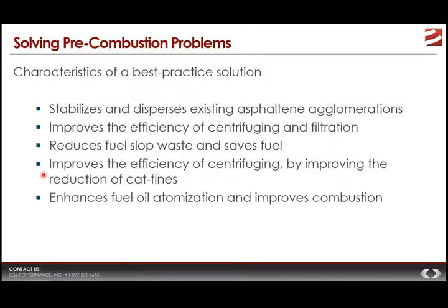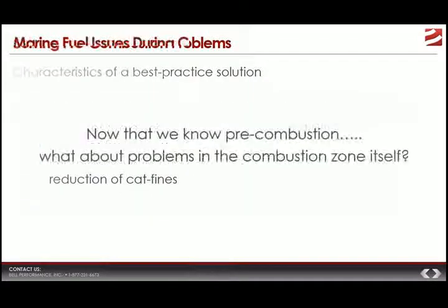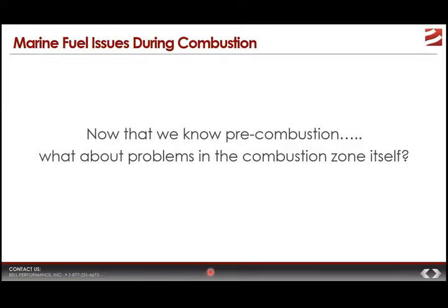And then, of course, a best practice solution should enable you to enhance your fuel atomization and improve combustion. Basically, what we mean by that is it's probably going to contain some kind of surfactant package that over time will clean the deposits out of those injector tips, which then over time will enhance the atomization of that fuel. So now that we know about pre-combustion, okay, let's move on to the second classification.